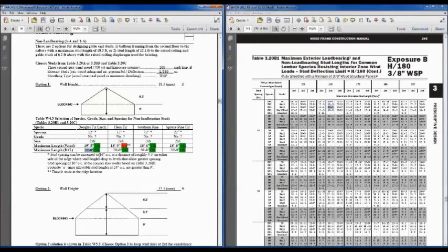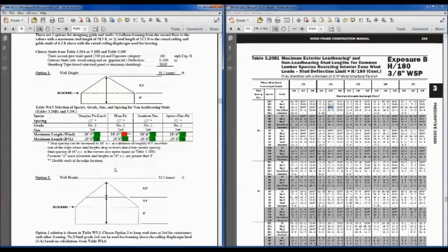So we could actually increase that spacing once you get to within 4'5" on either side of the ridge, where that height drops below 18, drops below what will work for 16 inches on center. So there's some things that you can do to get that spacing to work, but I don't know that you'd necessarily want to mix and match spacings in a gable end wall. But look at some of the footnotes on that.